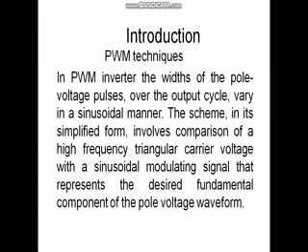In all kinds of inverters, we use some control techniques. The motto is to control the output voltage of the inverter. In inverter circuits, we use pulse width modulation techniques to control the output voltage. What do you mean by pulse width modulation? It is a control technique used to control the output voltage of the inverter by properly turning on and turning off the semiconducting devices inside the inverter circuit.